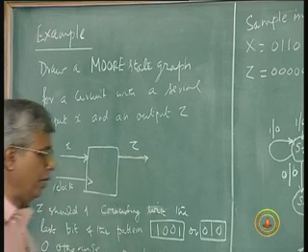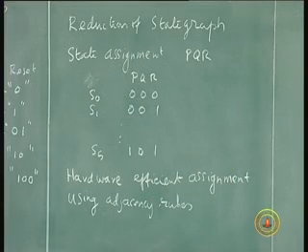And also this time we will not identify overlapping patterns. I will give you two variations. That means I should clearly have a 1 0 0 1, output will be 1, and that 0 1 will not be considered as a part of another sequence. Again it has to start with a 0 0 1 0, only then it can be a detected pattern. So, non-overlapping. So, I am going to reduce this. Overlapping of the patterns need not be considered.